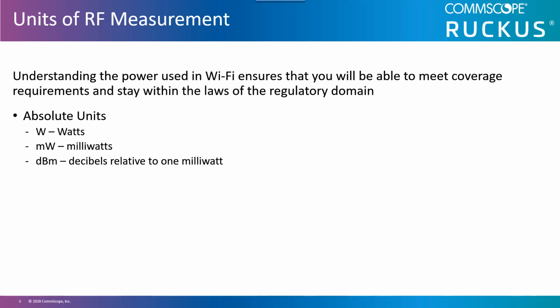The transmitted signal loses strength as it propagates away from the transmitter. You could be transmitting at 100 milliwatts from an antenna, but due to the distance, noise, and the sensitivity of the receiving device, you will never receive at that signal wirelessly. Remember, the signal gets weaker exponentially as it propagates away from the transmitter. That 100 milliwatt signal will be received as a strength so weak by comparison that it has a negative decibels measured value, such as negative 80 dBm, the strength needed for basic connectivity.